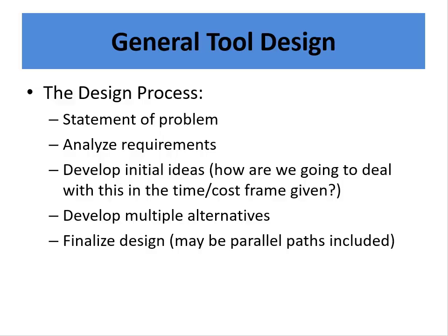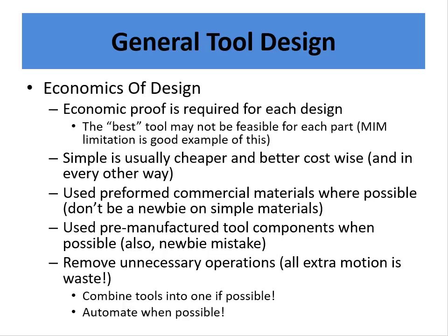And the parallel paths part comes from, if you have multiple different avenues of manufacture, the design is going to probably be likely different. So the way you would design a part that's machined out of a solid billet, you may do it differently if you're going to do it near net shape out of a casting or a MIM part or something like that. So it doesn't mean it's a different part in the sense of the way the specifications come to be met, could be the same, but the actual part itself is slightly different based on the manufacturing method.